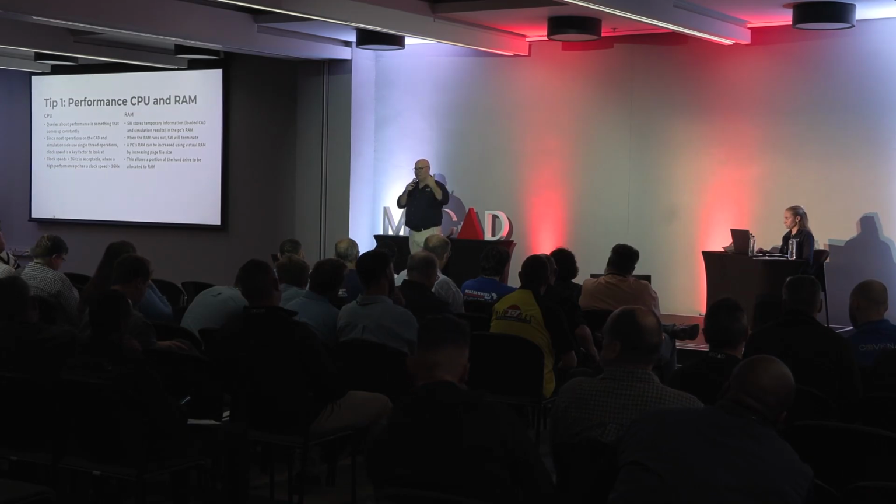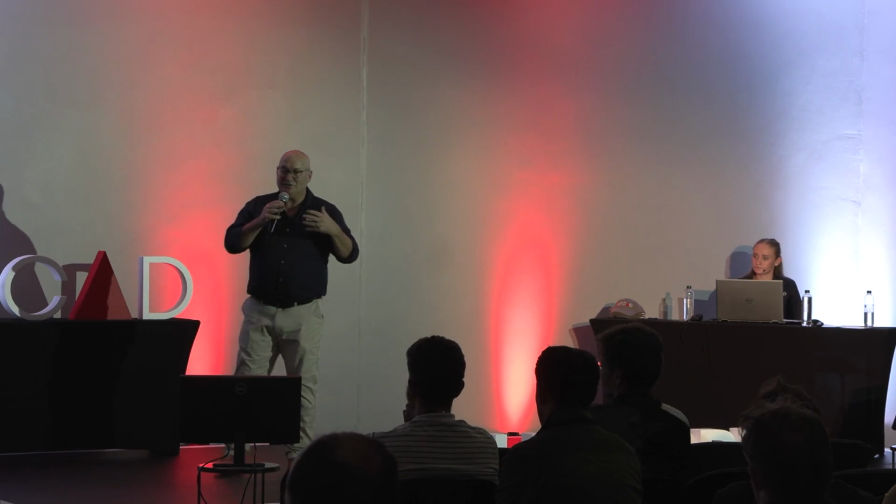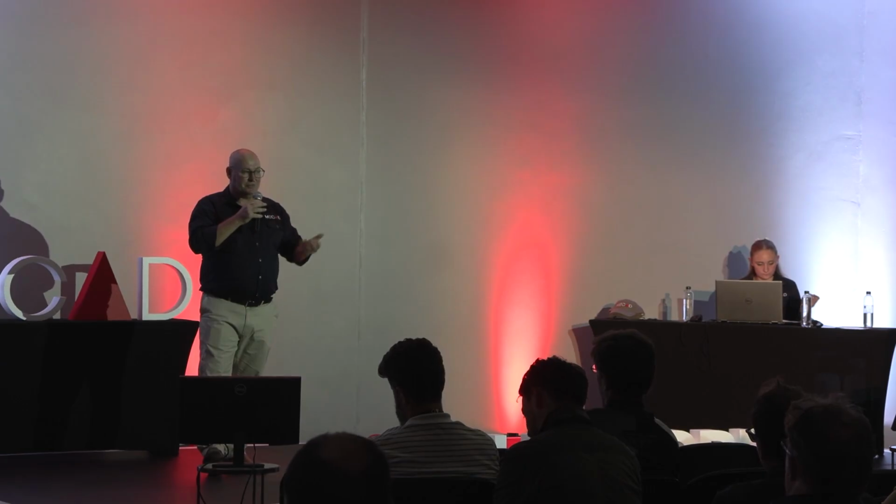It's just creating a massive amount of information. It's going to solve it again. It's going to recalculate this. It's looking for storage space in RAM. Okay, and there we do have a benefit by increasing the page file, and it will go and store on your hard drive as well. So if it's not a machine that's set up specifically with a lot of RAM for simulations or renders, you can benefit from that.